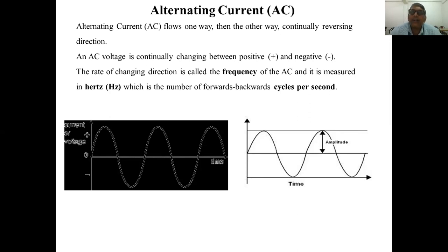Whereas a DC signal has a frequency of 0. It is always represented as a constant. It has no cycle and no frequency. If someone asks what is the frequency of a DC signal, the frequency is 0. And please remember, an AC signal has a positive and a negative half cycle, and one positive and one negative half cycle makes one cycle.